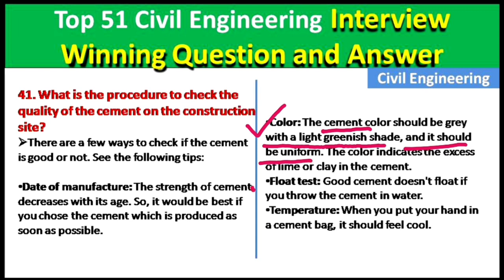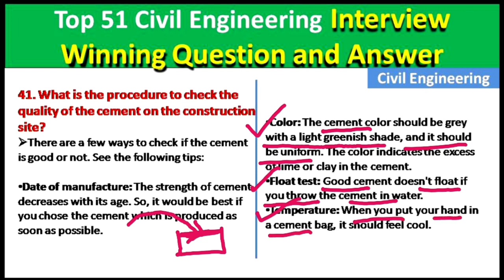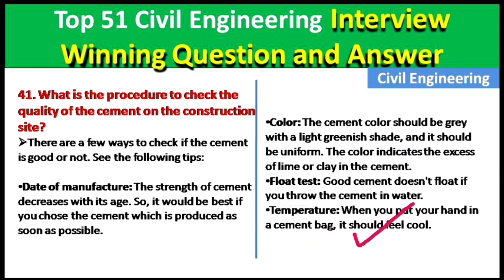Okay, now the float test. Good cement does not float if you throw it in water. Take a glass of water, and if we put cement in this water, it should not float. The last point is temperature. When you put your hand in the cement bag, what should you feel? Cool. You should not feel hot. So these are the methods to check the cement on site.